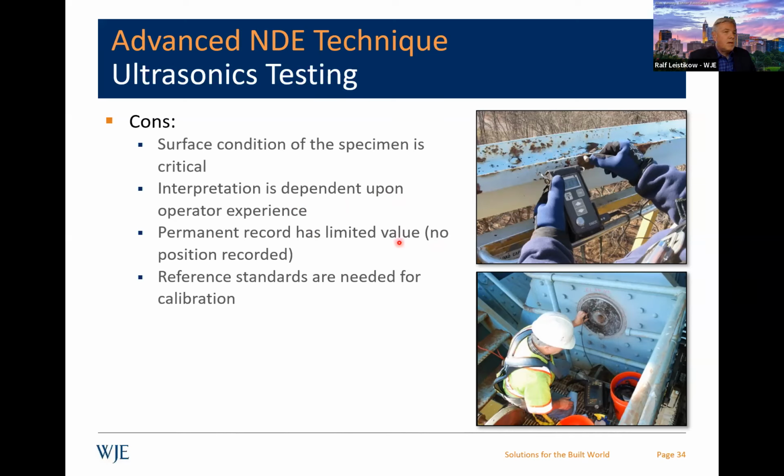So just keep that in mind. Other than the thickness readings, some of the instruments here are pretty basic. It is fairly easy, but some of the more advanced testing, where you're looking for fractures and things like that, you really need an expert to use it. Another negative is that you have to document the locations yourself. They're not automatically recorded with the equipment, so that could be an issue on some projects.